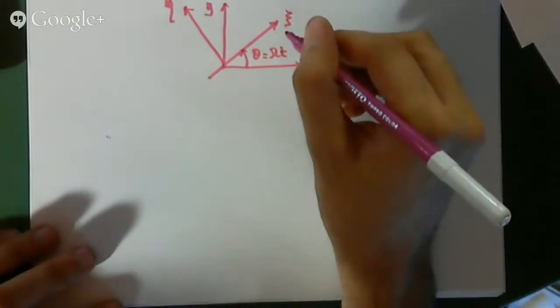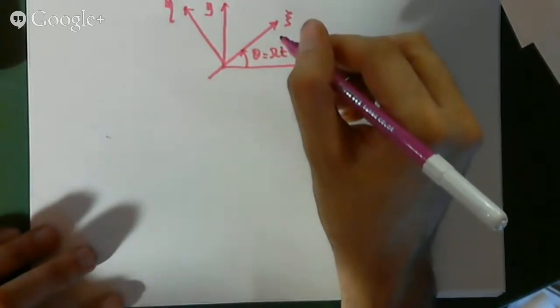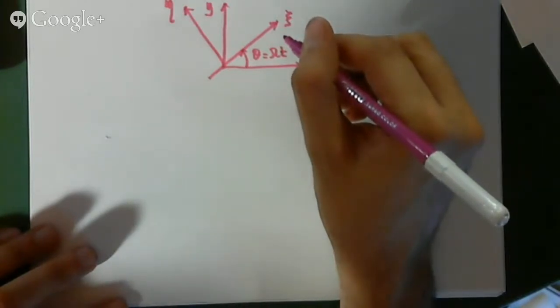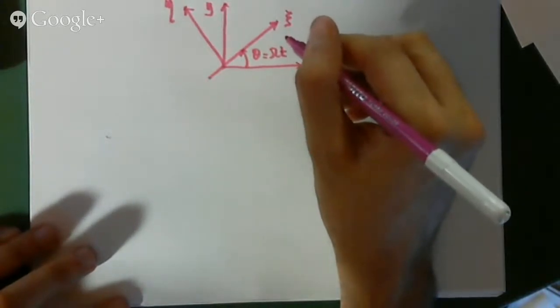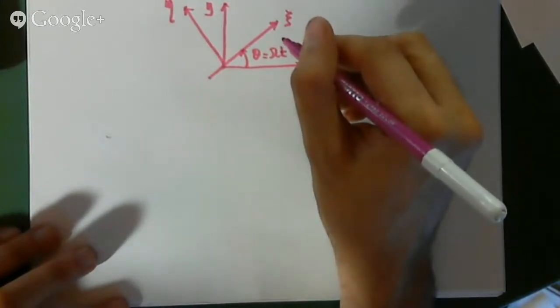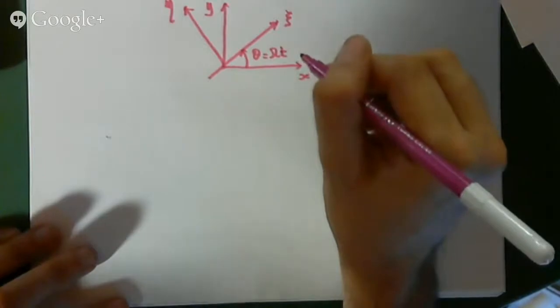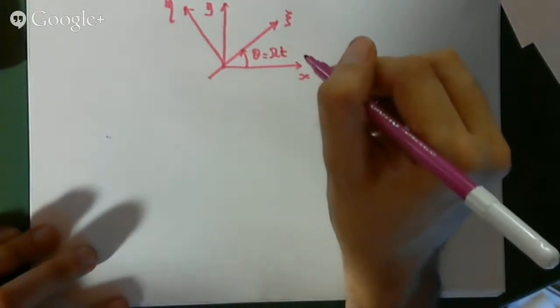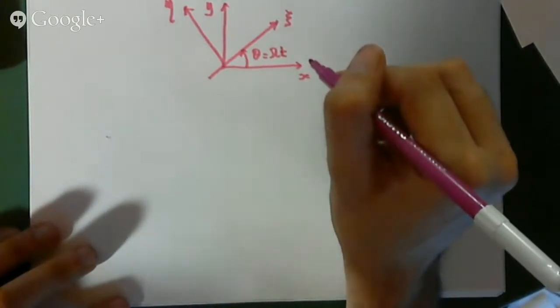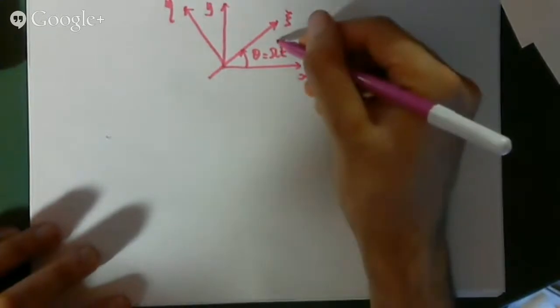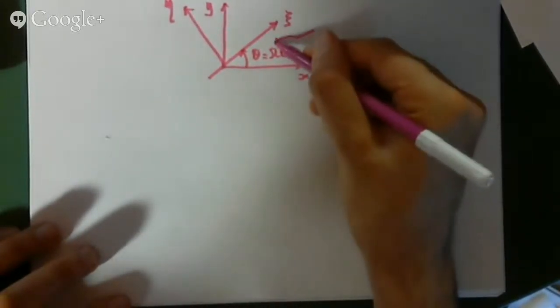The origin and z-axis of the rotating frame are the same as those of the fixed reference frame O, X, Y, Z. But axes zeta and nu rotate in the XY plane at the same speed of the rotor.